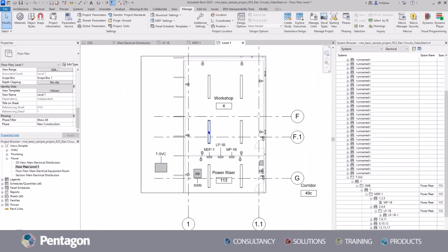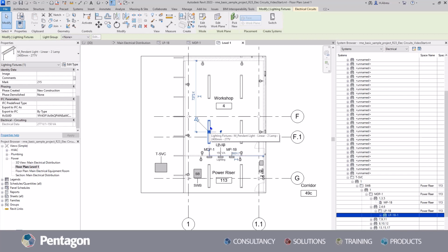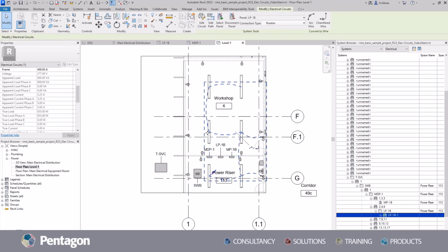Now when I select my circuit again, I can also turn my wires from virtual wires into actual wires, just by clicking this option that becomes available. These are temporary wiring, but I want to turn them into permanent ones. I can click on the option that I get in the graphics or in this command here to create arc wires.